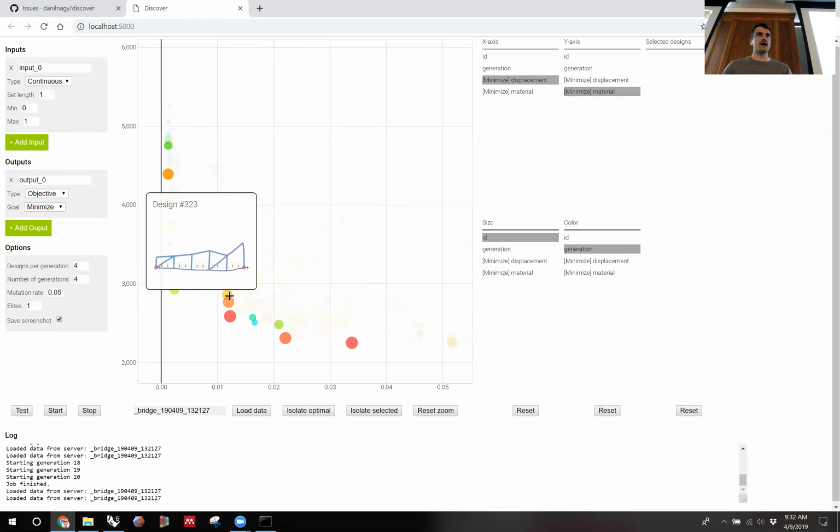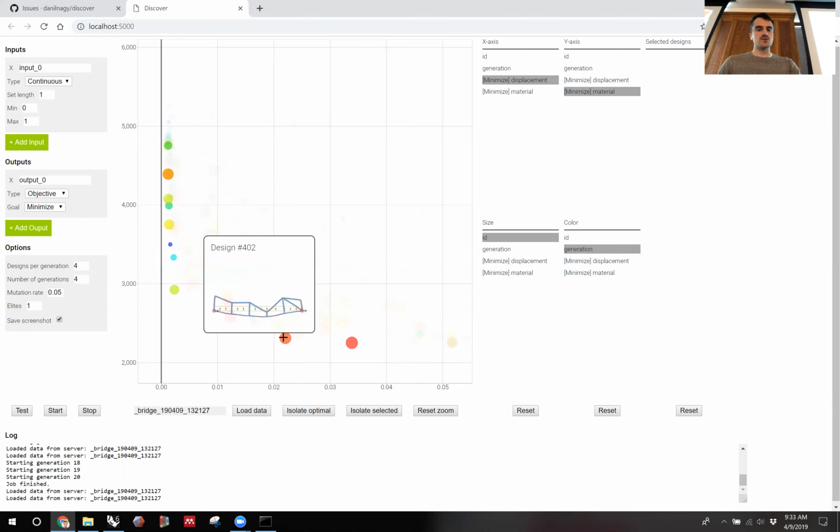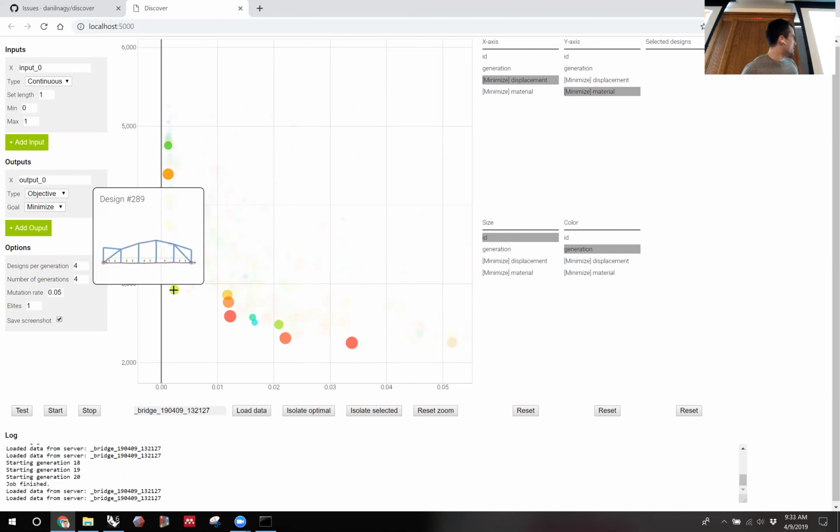And furthermore, in this example, I have another problem, because in the typical structural analysis, the first two objectives I mentioned, weight and displacement, are really important. Those are typically used as objectives. There's another really important criteria, which is stress, right? And the problem with this model right now is that we're not accounting for stress, which is why we're getting these designs that to the algorithm seem very good, but wouldn't work in the real world, because these designs might have a pretty good weight and pretty good stiffness, but we have no idea what's happening about the stress. In the real world, all three are really important, because you might have actually a theoretically stiff structure, which when the load is actually applied, the stress goes beyond the limitations of the material.